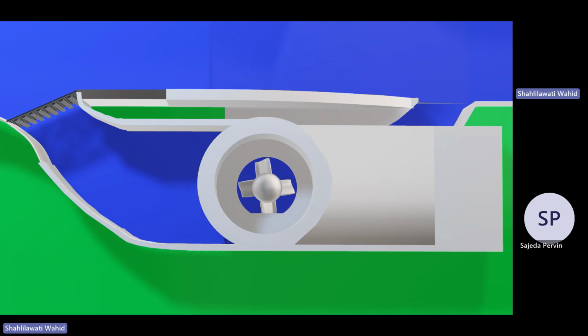And this is a zoom in of our turbine. This turbine is designed to be fish friendly, to prevent smaller fish from entering and getting hurt, injured or killed. Our turbine is made with a lightweight material, similar to aluminium, in order to spin easily and generate more electricity. Also, our turbine will be housed in a dome-shaped housing where water will be able to flow in a more efficient way, and our blades are angled at 60 degrees with 4 blades on the turbine.